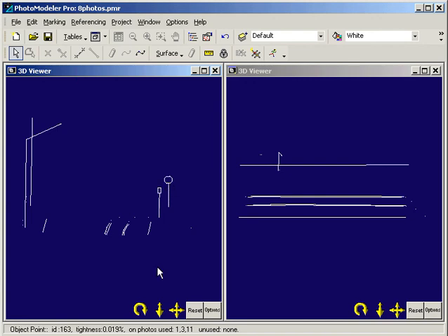Typically, at the end of a diagramming session of a road scene in PhotoModeler, you would export the data as DXF into a CAD package such as AutoCAD, AutoCAD Lite, AutoSketch, or Crash Zone. You would then complete the diagram using additional features to produce a scene diagram suitable for use in presentation in court. This concludes the forensics tutorial.